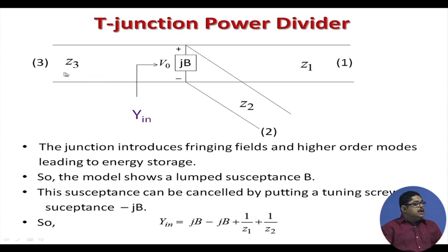So, this is the general structure. Suppose I am giving power at port 3, I want the power to be divided into 1 and 2 as before, but we have taken the characteristic impedances, equivalent characteristic impedance, or you can say wave impedance, that I will play with the impedance of the ports. In ports we can define characteristic impedance in an equivalent way. So, with either coaxial transmission line or waveguide, let us say these are the characteristic impedances. This line, that means the feeding line, generally we call it port 3 for T junctions, we are taking Z3, this is Z1, this is Z2.